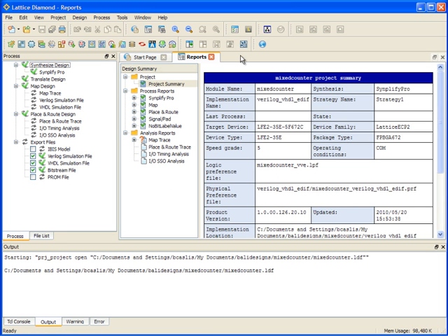And we've opened the project, and in the process list, you can see that the design flow is very similar to what you had in ISP Lever. The primary difference is now, instead of having a build database step, there are two separate steps for synthesizing your design and for translating your design. These two together make up the old build database step that you had in ISP Lever.